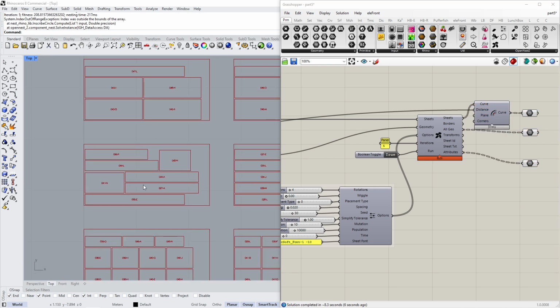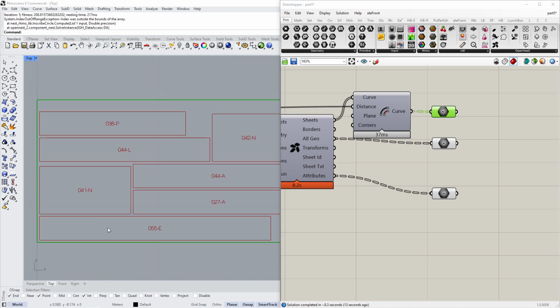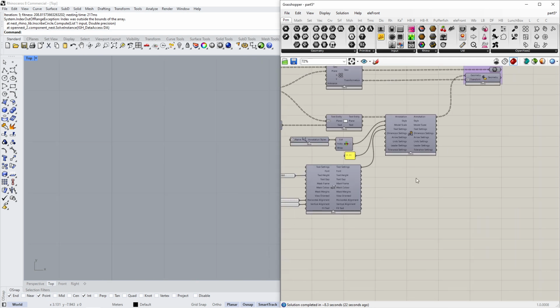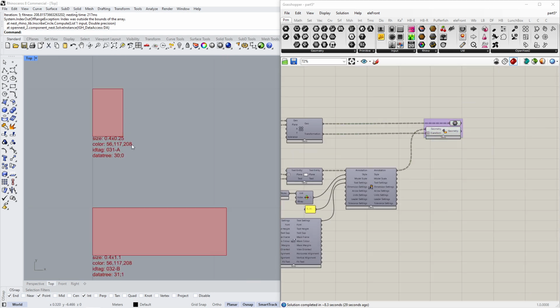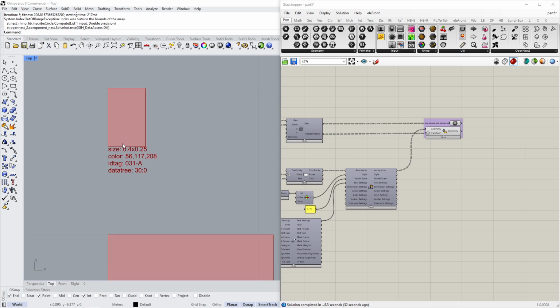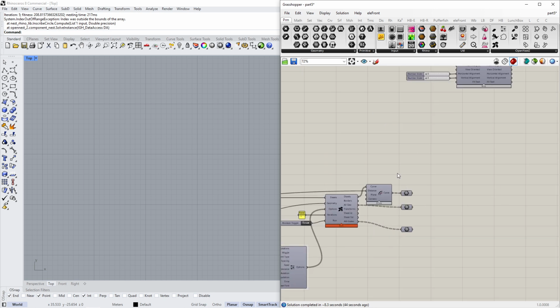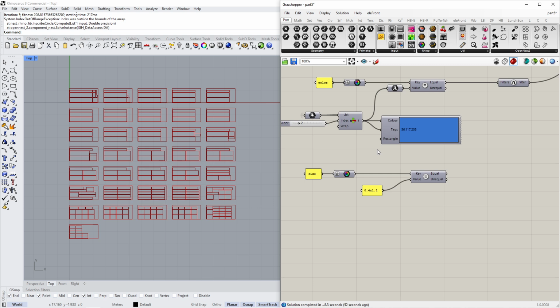These are the construction files that you can send to a manufacturer, like, hey, these are all the same colors. And the nice thing is every panel has a tag, so you can keep track of it. And if you don't really know where that tile is located, that's why we did the previous setup, for every tile having the key value pair attached as a certain text. So you can look up the ID tag and know exactly the size, the color, and where it's located in the facade. That way you can really quickly switch between your different colors, put another color, and spit out construction drawings fairly quick.